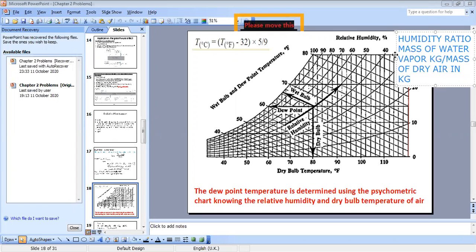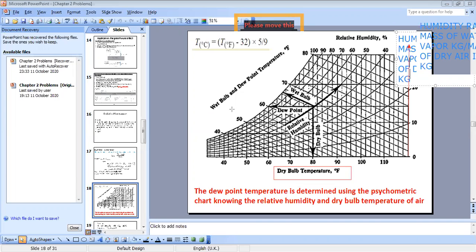Now, this is the first property in the psychrometric chart. The other properties: you have the dry bulb temperature, which is here along the x-axis. Now, you have the wet bulb temperature given by the following curve. So this curve here, the values of temperature here correspond to the wet bulb temperature and also to the dew point temperature, and we will explain what is the difference between the two.